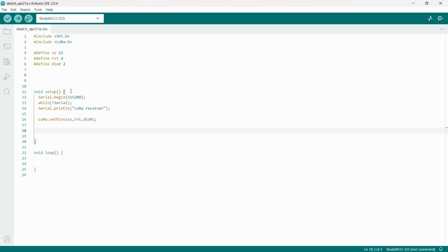Next, we have to set the frequency. The LoRa frequency will be different as per the location. When it comes to Europe, it will be 866. When it comes to North America, it is 915 megahertz. But we are in Asia, so we are using 433. Sorry, 433. Okay. We have to wait till this frequency is initialized.